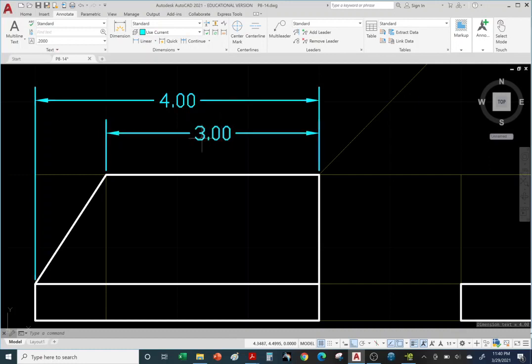And text height, if you're following the American standards, is typically about 0.16 inches or 0.18 inches in height. If you're using international standards, it's about 3 millimeters in height. This should already be set up for you. If you go work for a company, they should already have a standard that they're following, whether it's an American standard using inches or an ISO standard with millimeters.